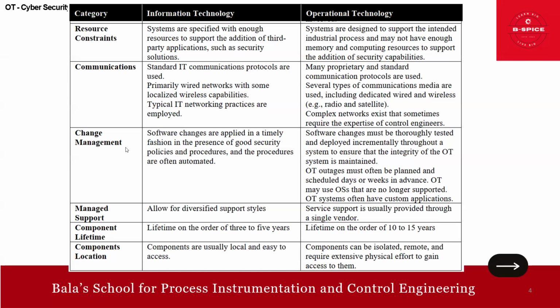That's about the communication. Then when we talk about change management, in IT, software changes are applied in a timely fashion in the presence of good security policies and procedures, and the procedures are often automated. Here in OT, software changes must be thoroughly tested and deployed incrementally throughout a system to ensure that the integrity of the OT system is maintained. Very much important, right? So OT outages must be planned and scheduled weeks in advance. OT may use operating systems that are no longer supported. OT systems often have custom applications. That is on change management.